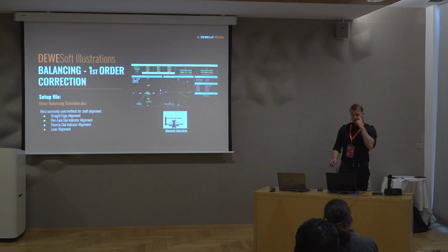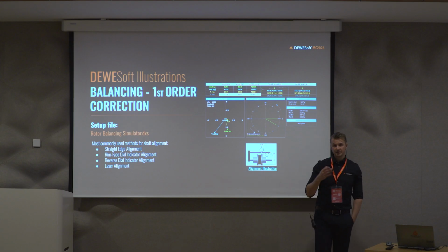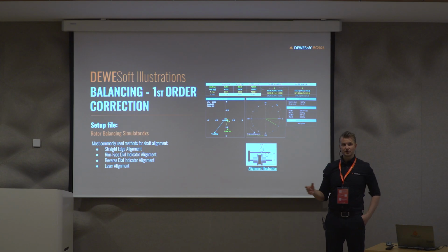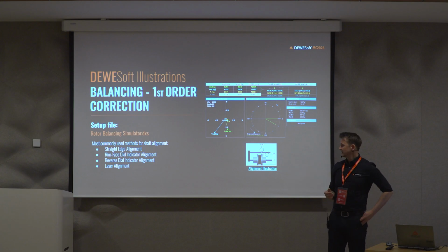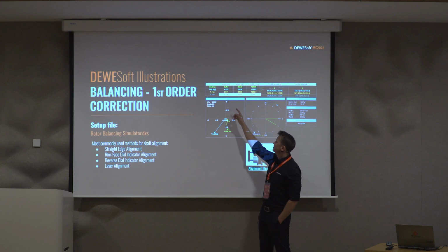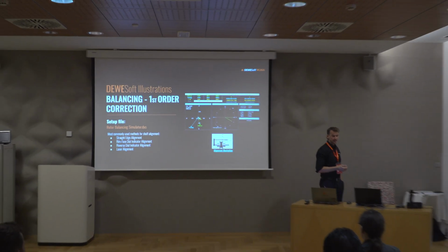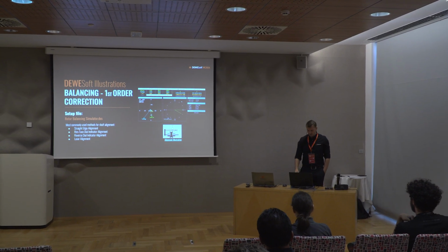When we want to take care of, for example, imbalance, we can use our rotor balancing application where we mount an accelerometer or a prox probe, and we measure the speed. Based on that, it can tell us exactly where to mount mass in order to make the center of mass aligned, and the vibration level will become less and less the more you do this. So if you have any interest in rotor balancing, we can talk more about that. Just come to me.